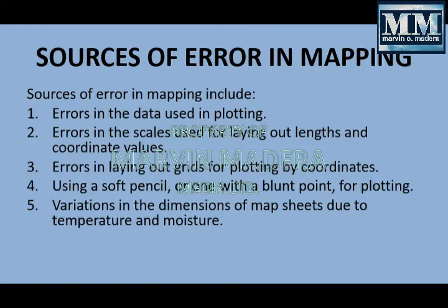Errors in scales used for laying out lengths and coordinate values. Errors in laying out grids for plotting y coordinates. Using a soft pencil, or one with a blunt point, for plotting. Variation in the dimension of the map sheet due to temperature and moisture.